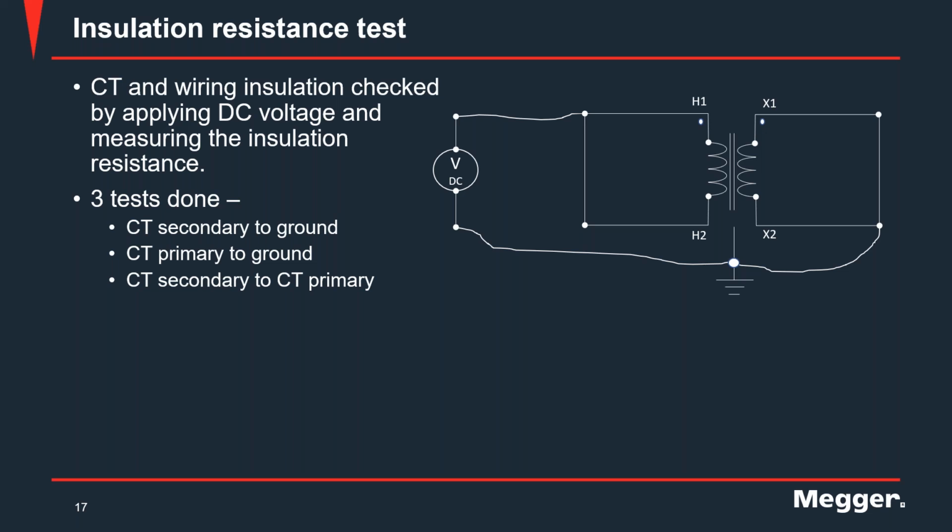Okay, good, interesting question, because definitely those CTs are out there, and they're common in generating facilities. When you use the conventional or traditional method of applying voltage to reach the knee point, if the knee point is that high, around 30 kV or anything above 2 kV, which is the standard voltage of CT testing equipment, then you're going to be limited because you cannot reach that voltage.